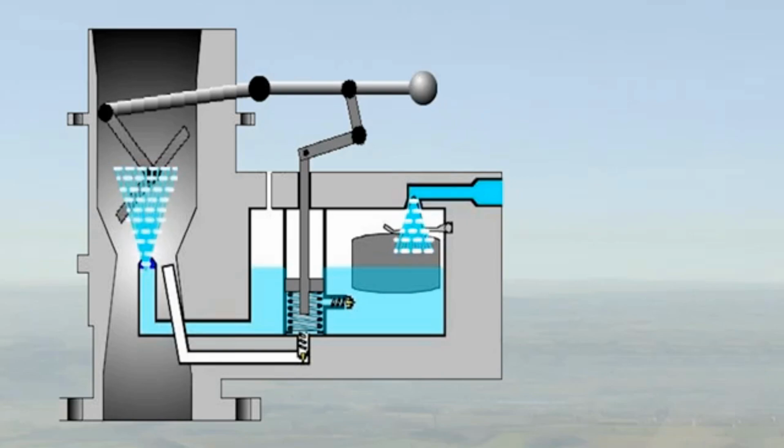In some pumps, a controlled bleed past the pump piston allows the throttle to be opened slowly without passing fuel to the engine. In other pumps, an additional delayed action plunger is incorporated to supply an additional quantity of fuel to the engine for a few seconds after throttle movement has ceased.